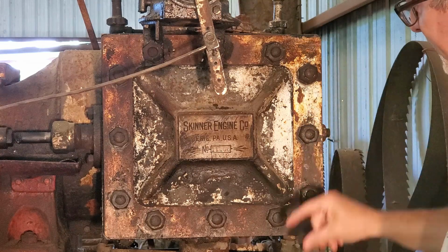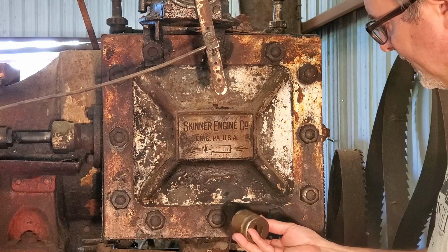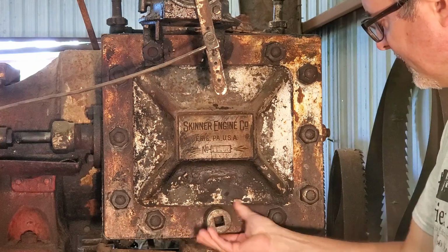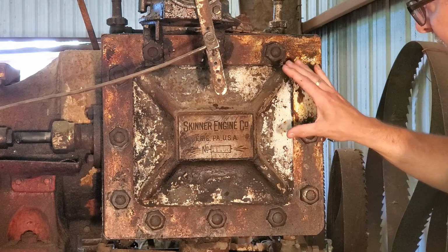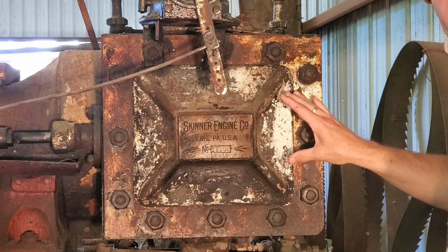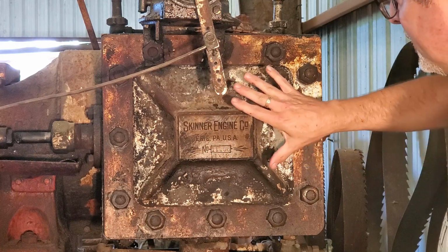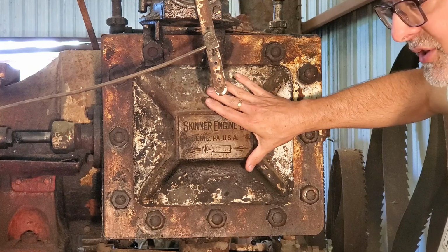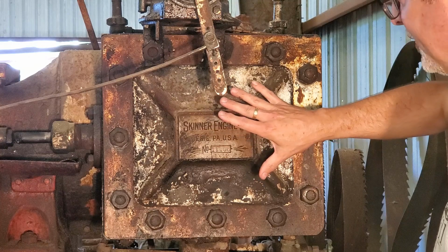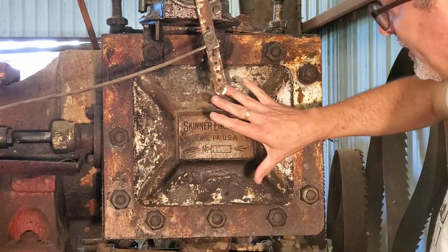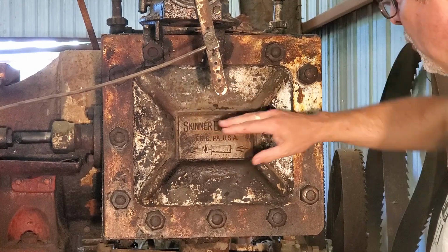Okay, the steam chest cover has, I believe these are 3/4 inch studs and 1 7/16 hex nuts. So this is pressurized, in this case, to 150 psi. And normally on a conventional slide valve engine, the valve is seated against the face of the valve ports by the pressure in the steam chest. And when you pressurize the steam chest, that valve will actually snap tight against the valve ports.